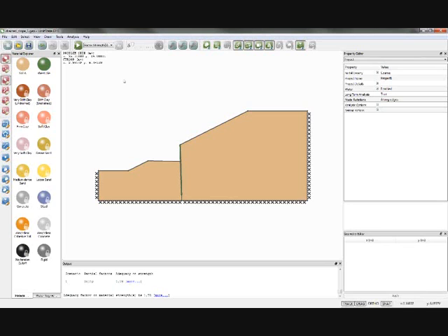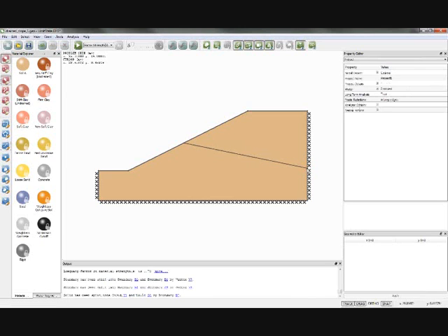What I'll do finally, just as we're nearing the end of the webinar, is click undo and revert all of those changes, and we could look at slope reinforcement. Discussion of reinforcement is beyond the scope of this presentation, but I'll just show one example of adding a soil nail halfway up the slope. So again, it's a similar process. I'm going to click here and draw a line like that. I'm going to add a vertex about there, and I'm going to create a new material.